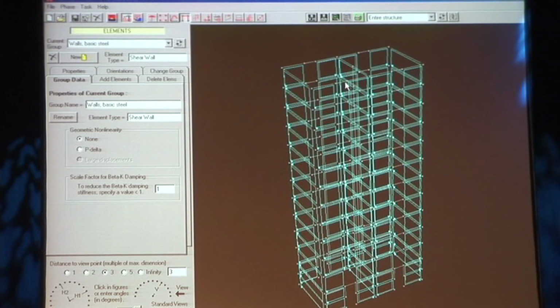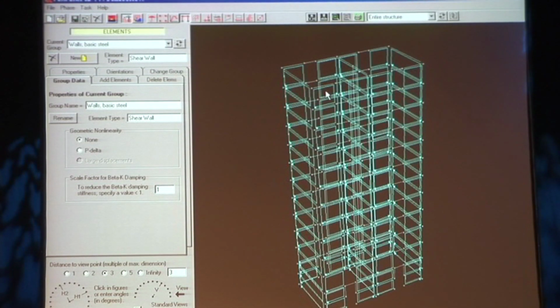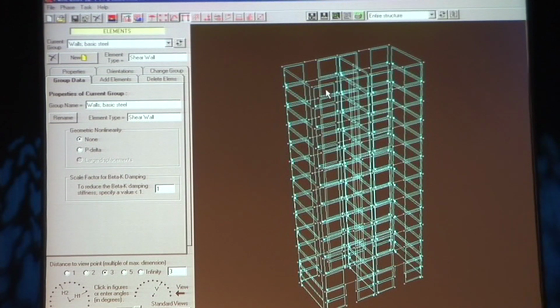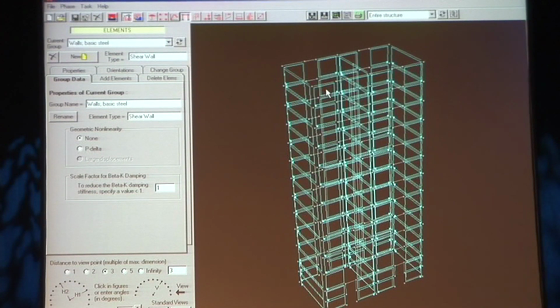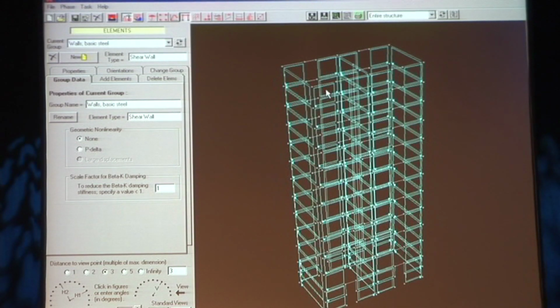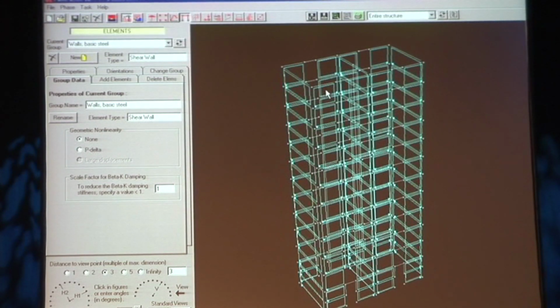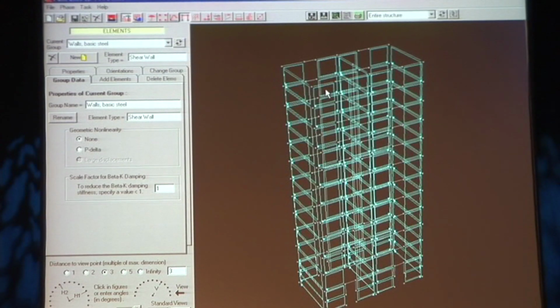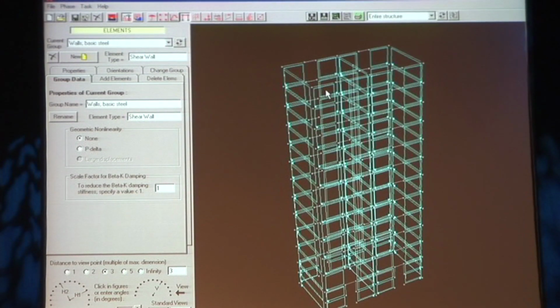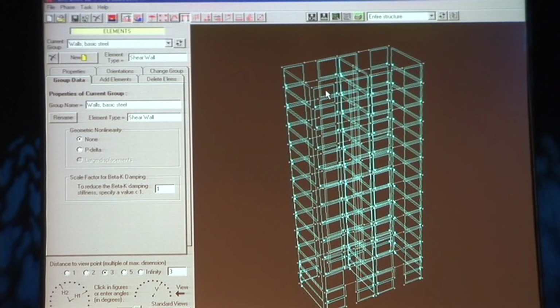The way it has been set up is it uses fiber sections over the whole height. And the reinforcement varies over the height for axial bending effects based on the moment envelopes that were calculated from a linear analysis. And then the shear strength actually in my model is constant over the height, but that's kind of a detail.